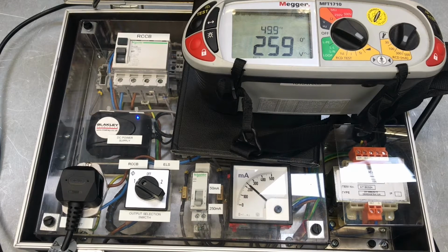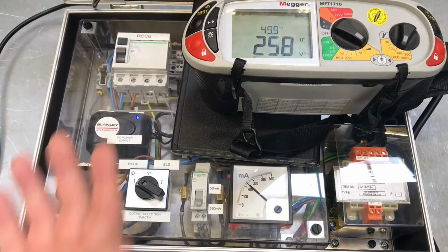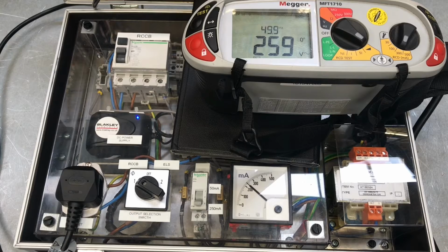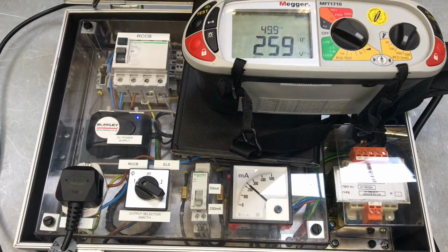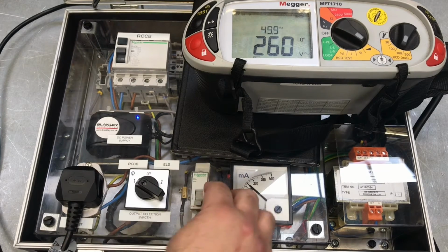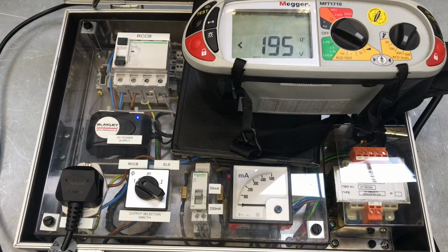So if you do have that, this is why I suggest you go through that sequence of test, check the button. A perfect example of this was I worked on Docklands Light Railway, third railway traction system. During the day, I could walk up to an RCD, push the button, and it did nothing. But when we did the electrical inspection and testing, when would you do that on a railway? Yeah, when it's closed down. When it's closed and there's no traction power. So when it's closed and there's no traction power, guess what? Passes the functional test. Great.